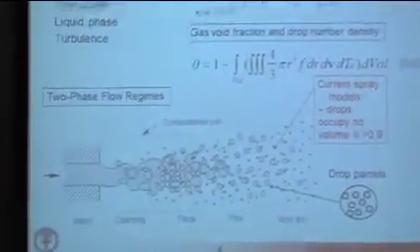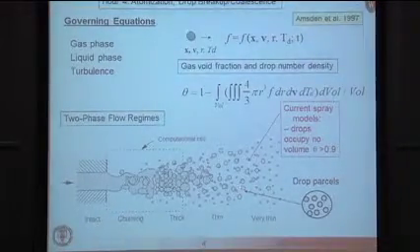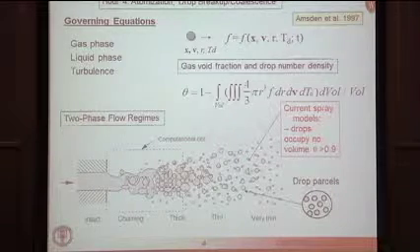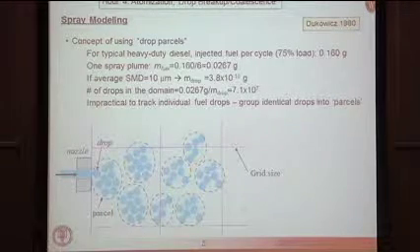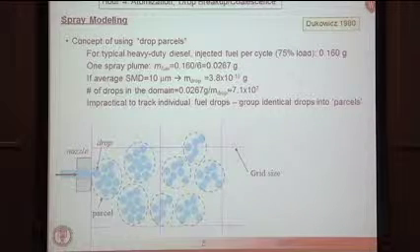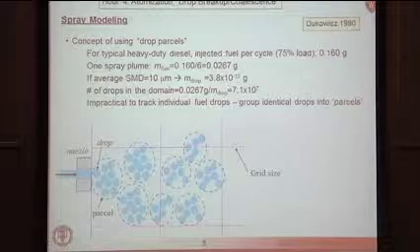The other thing is that, as you'll see on the next slide, a spray consists of many, many droplets. And so one approach that is used is, instead of treating individual droplets, to essentially group them together stochastically. This was an approach that John Dukowitz introduced that basically made spray modeling possible. It was a major advance. And the idea that he had was this.